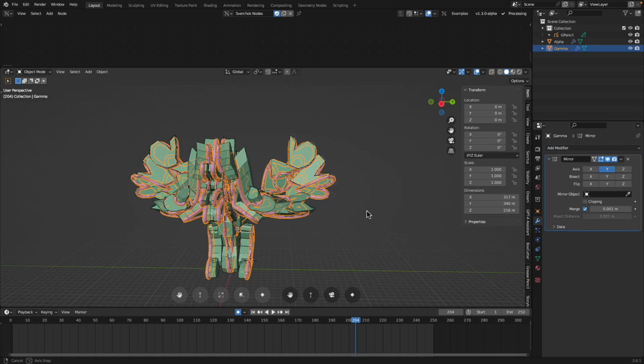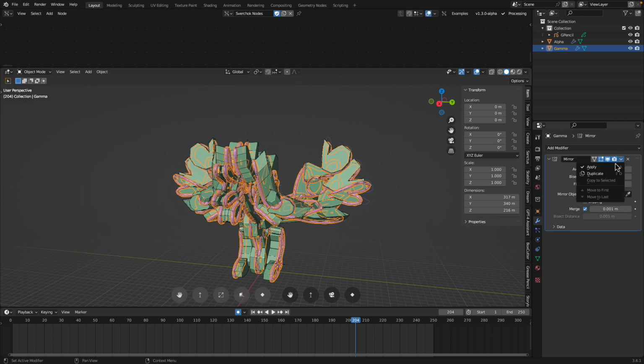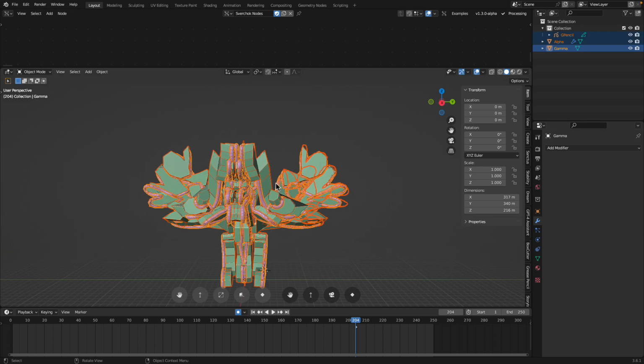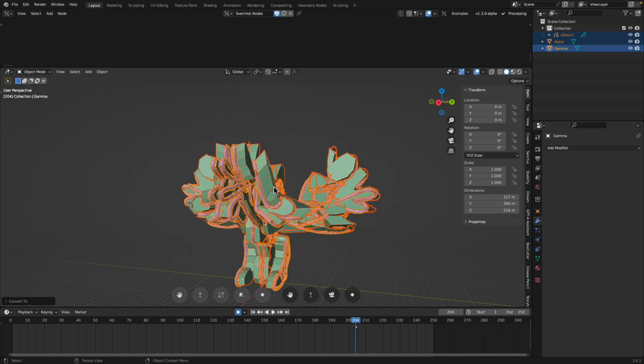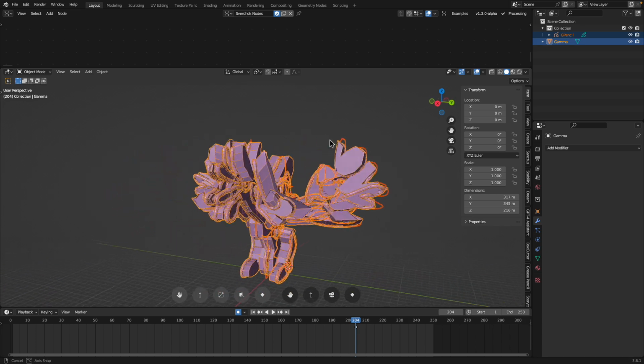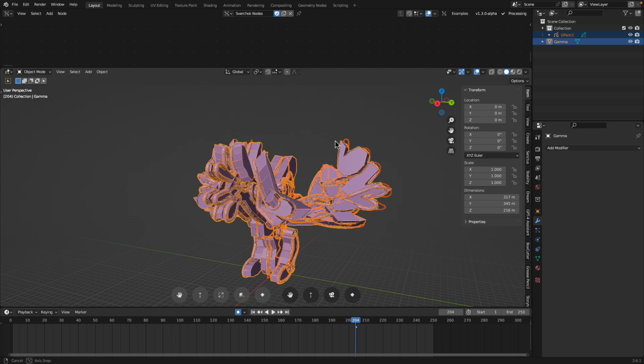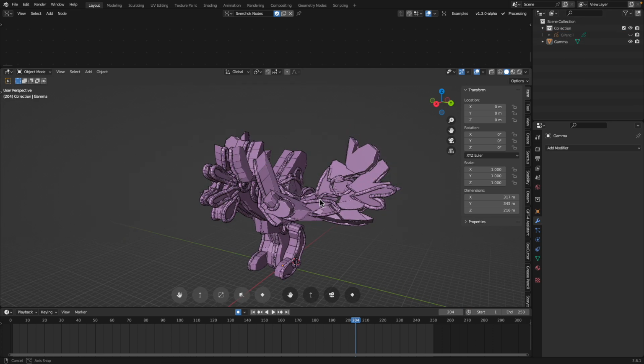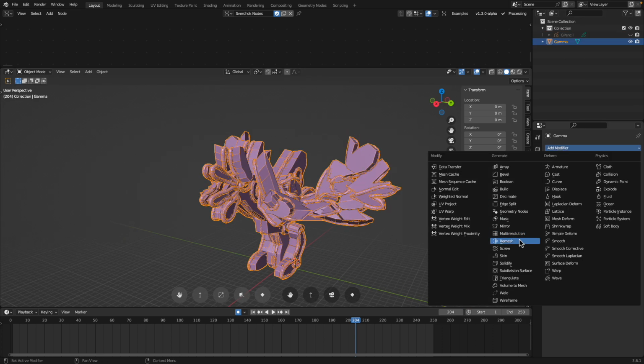Okay, we chose the wrong axis, but now it's correct. Select everything, join them as one. Okay, right click, convert to mesh, apply the modifier, join everything, grease pencil turn off. We can remesh. Hopefully it's not too complicated. Hopefully Blender can handle this.